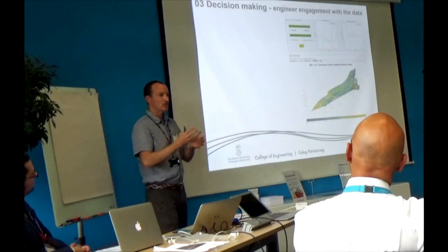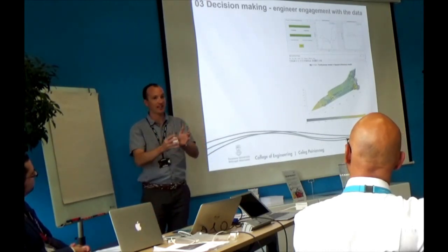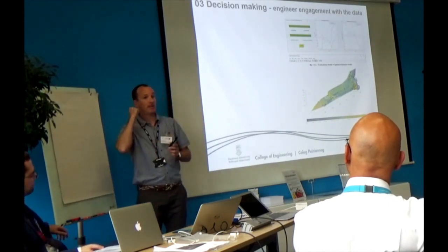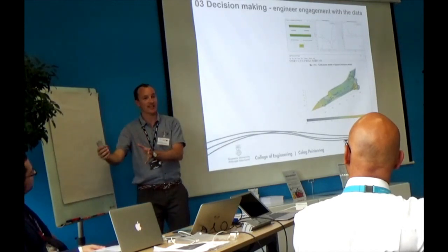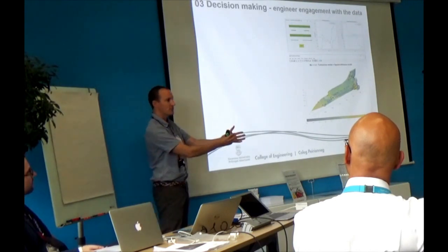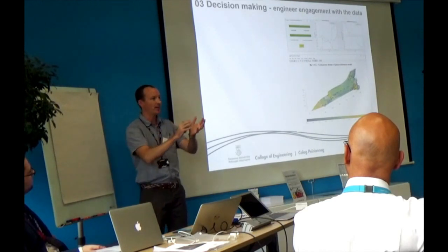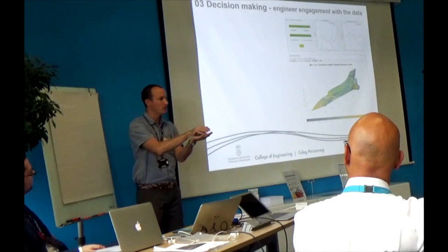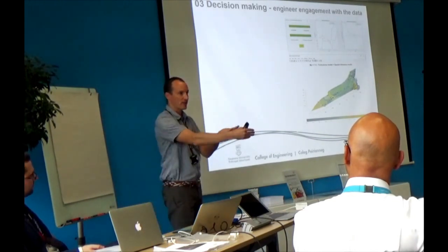And we're starting to ask questions about how we, in a meaningful, intuitive way, allow design engineers who may not be CFD experts, they may be aerodynamicists with no CFD experience, who will be sat at the side of the desert after a run. How do we meaningfully allow them to engage with the CFD results and data from those pressure sensors, and try and identify where those two sets of data are mapping well, where they're not mapping well, and which models would be the best ones to use to try and predict what will happen on the next run of the car.